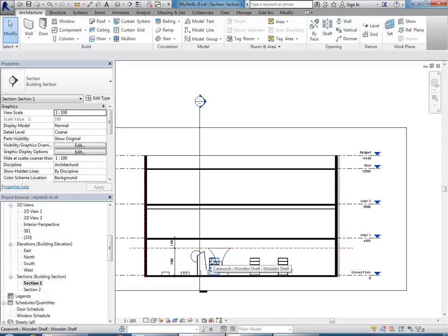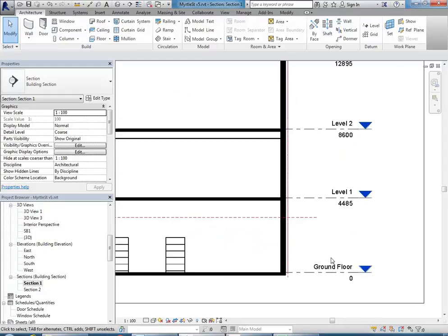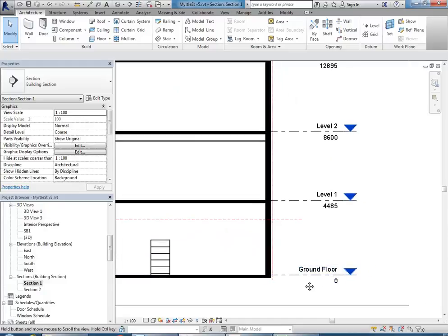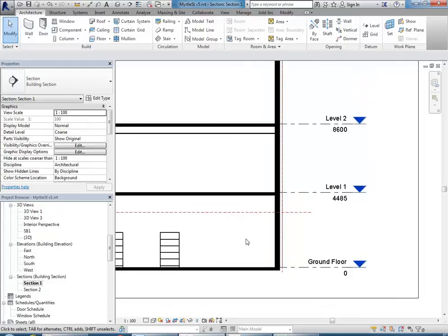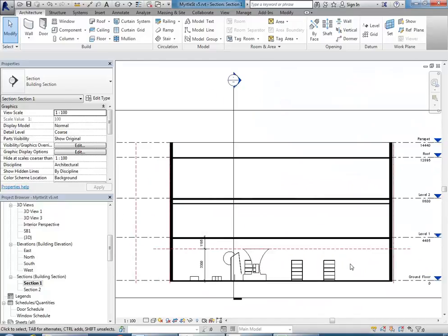So when you're working at ground levels, you've got to do a lot of site works and moving dirt around and checking the slopes and doing accurate surveys and things like that. And again, that's not a problem with Revit. You can easily move levels up and down slightly as long as your objects are tied to them properly. So floors, walls, ceilings, roofs, they can all be associated with your levels.